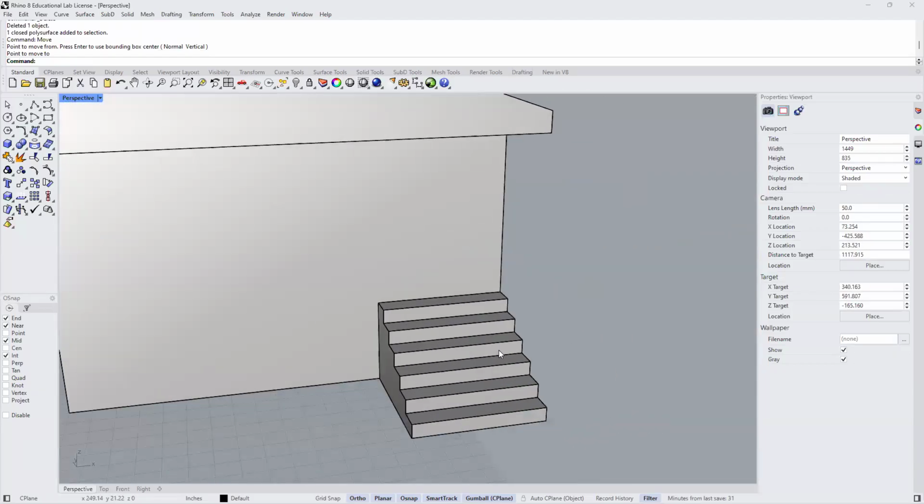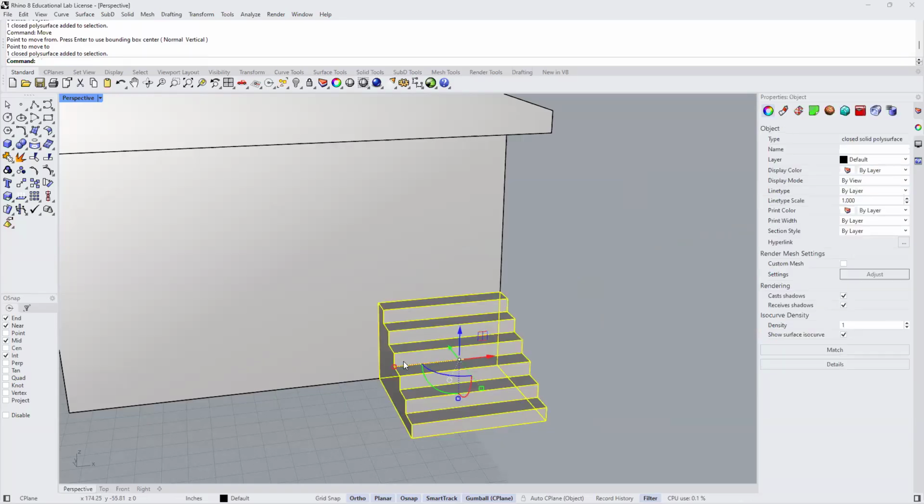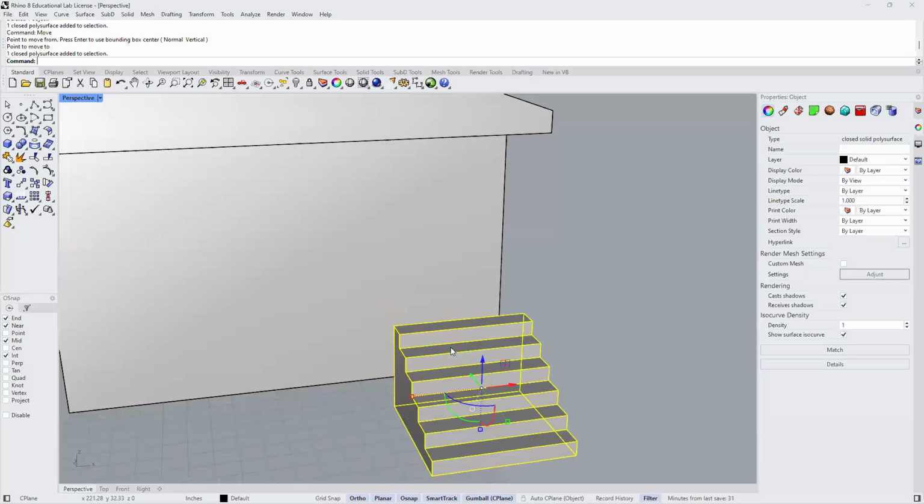And the other thing I'm noticing also is that there's nowhere to stand. When I come walking up to this house and ring the doorbell, it's really tight there. So what I'm going to do is I'm going to take the steps here. I'm going to click on the green arrow, and I'm going to say move it back -3 feet like this.